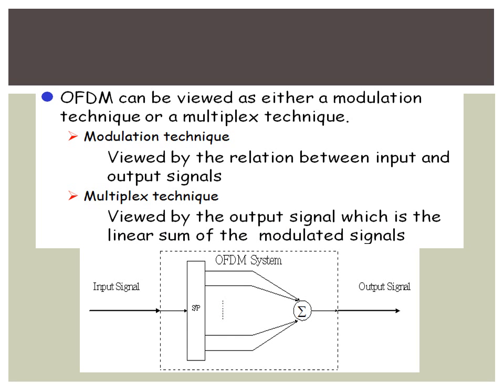Now, OFDM can be used as a modulation or multiplex technique. It depends on the application of the user. If it is used as a modulation, then different types of modulation, that is ASK, FSK, PSK, are preferred. But if it is used as a multiplex, then no modulation process is required. Only a number of carriers are combined with each other, and at a proper timing we are sending only one data. This figure indicates the multiplex technique.